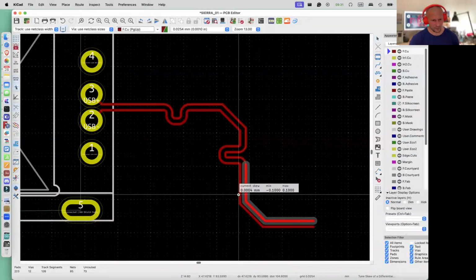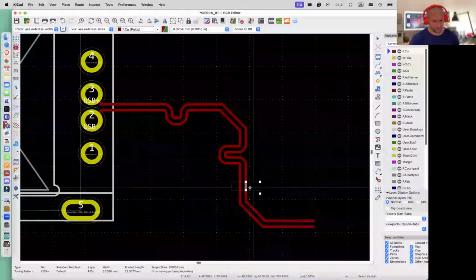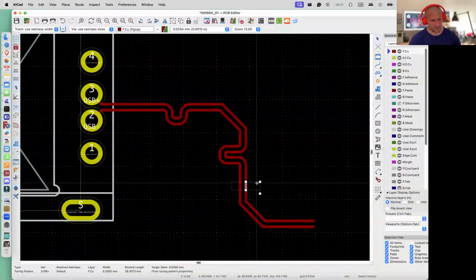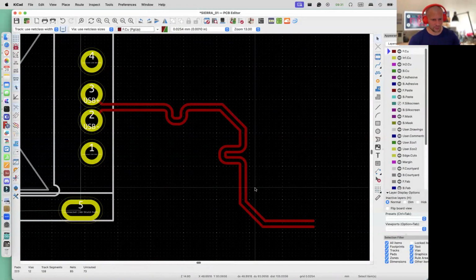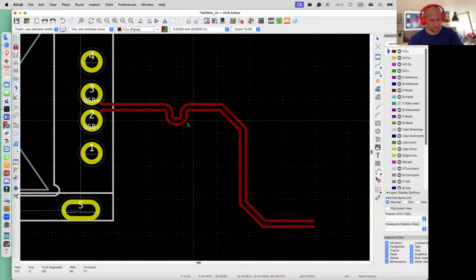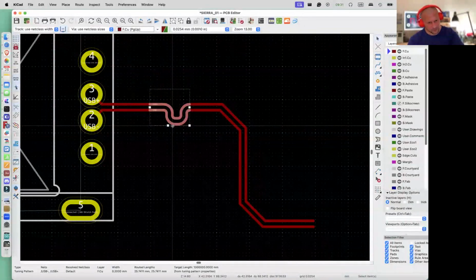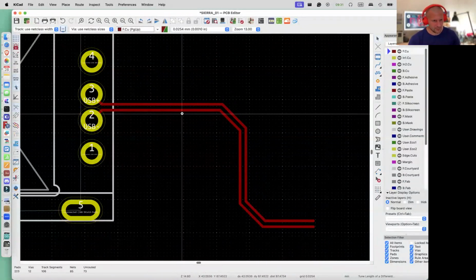And when you click on the differential pair, there is a new feature, as I said, in KiCad 8 for manually modifying the meanders, but it cancels the function of the skew tuning. So I need to delete manually those manually changed meanders and place them again.